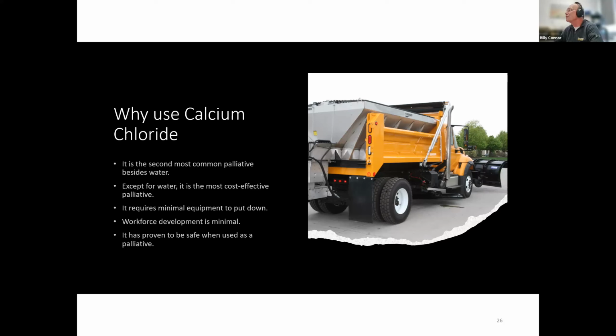And to answer your question, Leanne, about it being corrosive: as a salt in and of itself, it is very corrosive. However, we're putting that down at only, we'll talk about it in a minute, but we're only putting 1 to 1.5% of the salt down in the soil. So it's very minimal. And we really haven't seen much issue with corrosion once it's in the soil. But we'll talk about how to take care of the equipment that you're using to put it down.